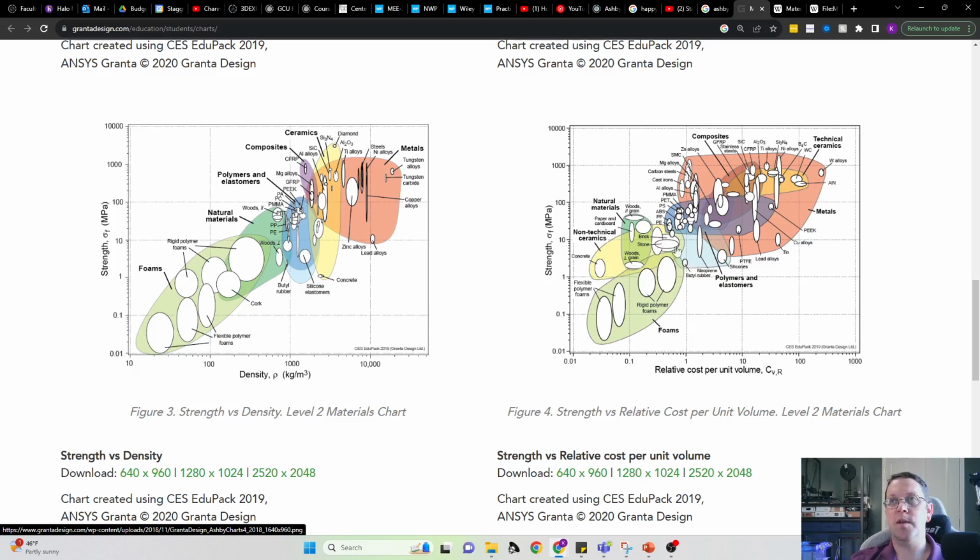So stone, brick, those sorts of things. These are why, depending on availability, brick walls sometimes have to be a little bit thicker than composite walls made of wood. Stone is similar. Stone has a much narrower range of strength. Rock behaves like rock, weirdly enough. There are different densities, but they all have similar mechanical properties. Same thing with bricks. They do what bricks do, and that's all they do.